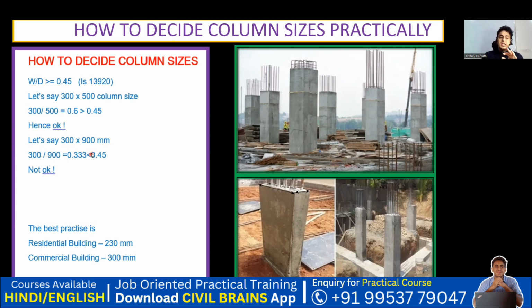But again, you don't have to always do this calculation. I'll be giving you certain column and beam sizes. You can always take those as ready sizes and go with the calculation. So the best practice is that for the column, if it is a residential building, you can go with 230 mm as your minimum breadth. And if it's for a commercial building, go with 300 mm as your minimum breadth of your column.